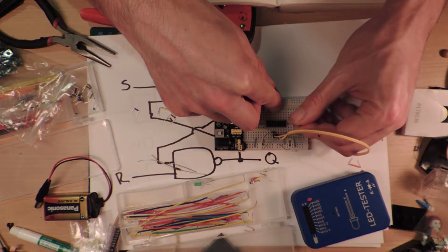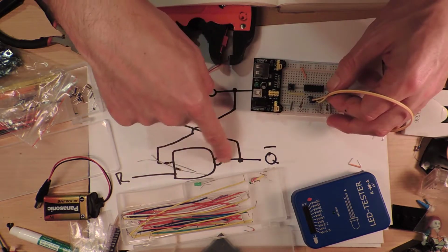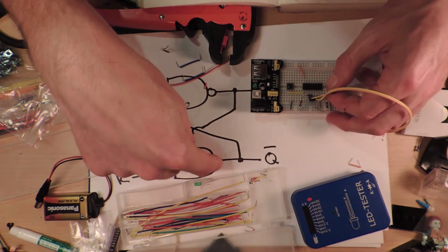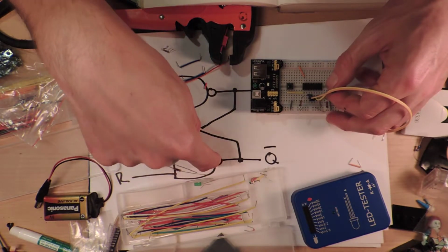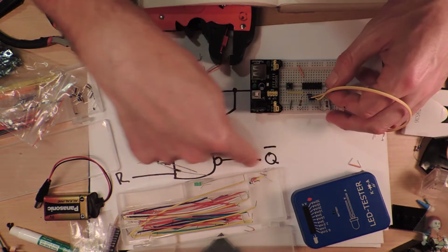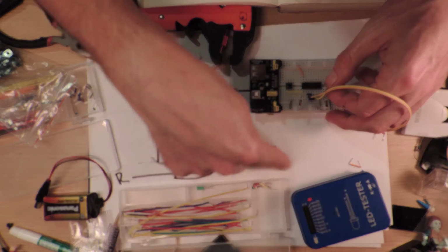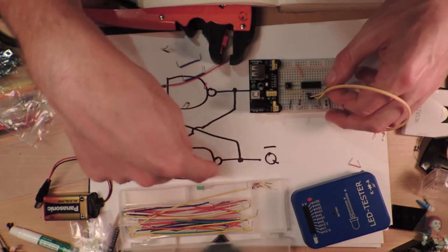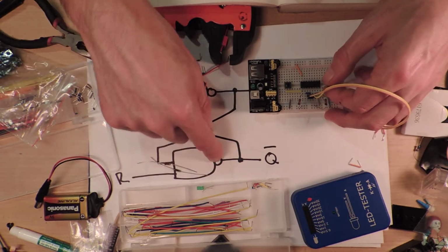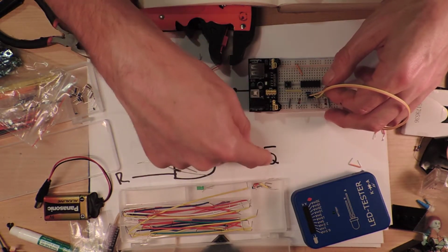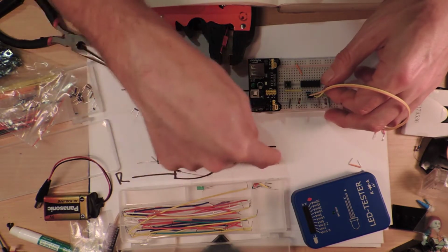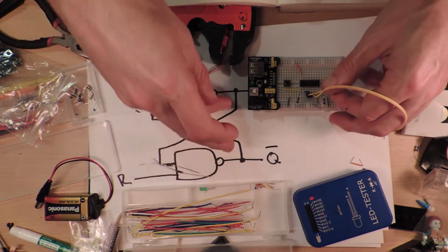So the other way of doing it is that you can have a positive voltage coming in here and going into the output, and when this is low, it will sink current because you've got a positive voltage here and it will go into here to a low voltage, and it can sink more current if you do that. Whereas the other way of doing it is you have this LED connected to ground, and then this has a high voltage, and then the current goes that way.